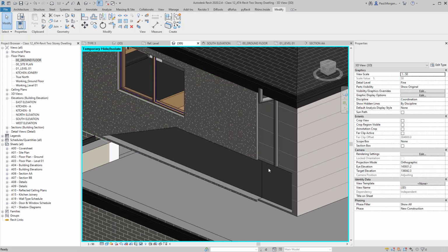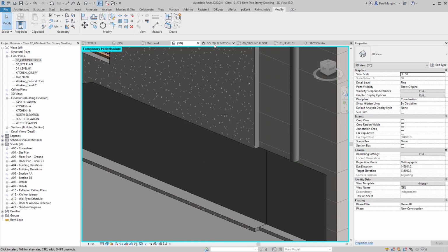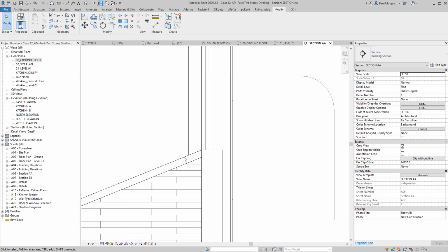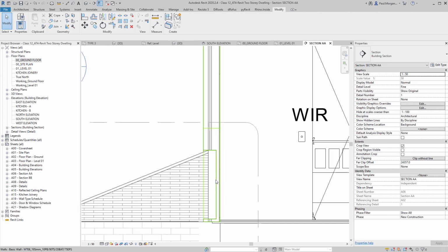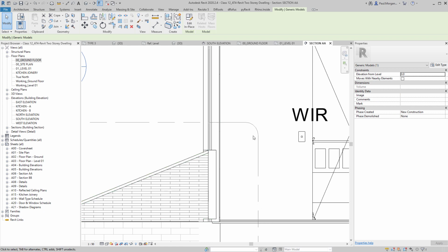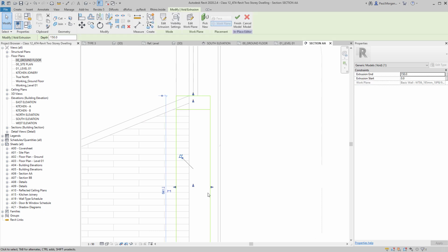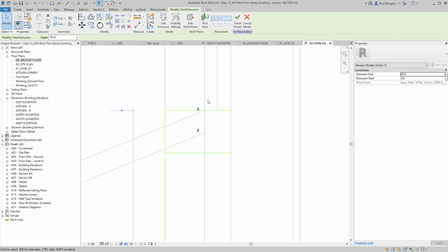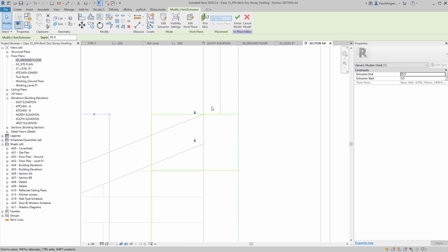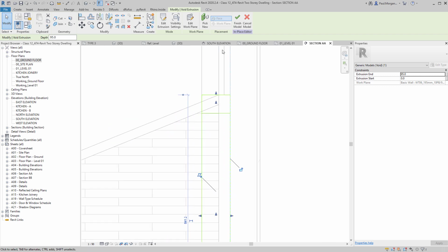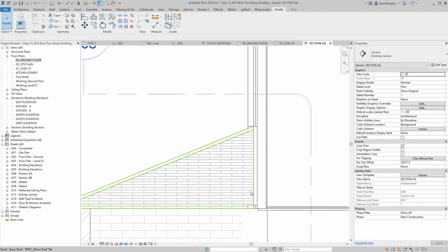Now we need to make sure that we're not cutting too far into this wall. So this is where going to the section helps. So I'll go to the section. Okay, there's that void extrusion. Now I'm hitting tab to select it, and once I've selected it, I know I have, because it will come up with the modify tab and it will say edit in place. I click on that, and now simply I can move this wherever I want. So I can click on this void extrusion and I'll move it back to here so it's flush with the timber stud. Notice now we're cutting the weatherboards, and we're cutting the expanded foam right on the joint of where it meets the stud wall. I'll say okay. And that's now complete.